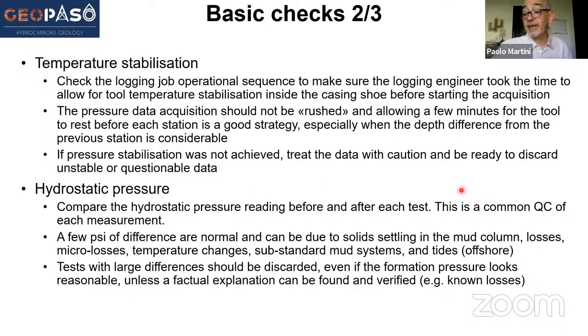And if that was not done, you should be treating the data with caution, and you should be ready to drop from the interpretation unstable or questionable data. And then the check that is always recommended is also the hydrostatic pressure. So check that the difference between the hydrostatic pressure reading before the test and after the test is within a few psi. The difference, there's always a difference.